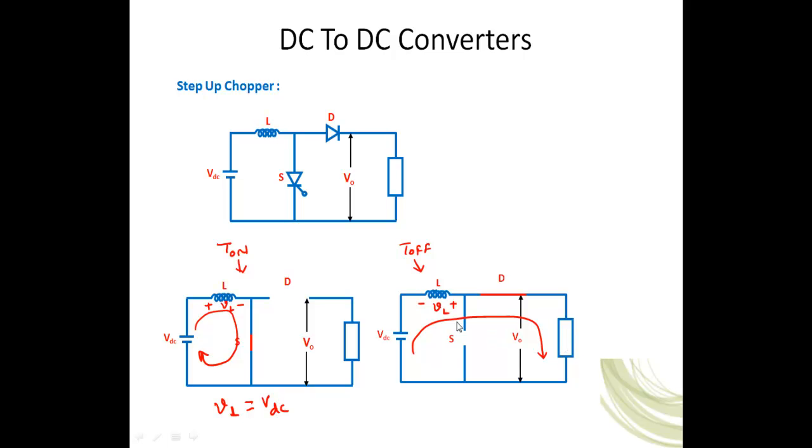load. So by turning on the switch, we are making this one an intermediate source, and then both are supplying together to the load. That means the instantaneous source plus this permanent source, both are supplying, and that's why we get more energy here. That is why we can increase the output voltage.